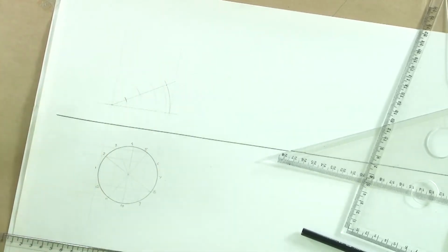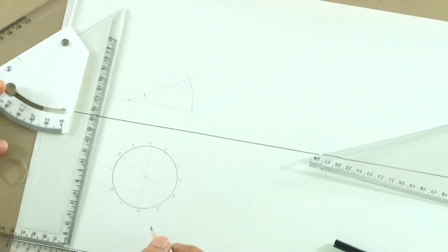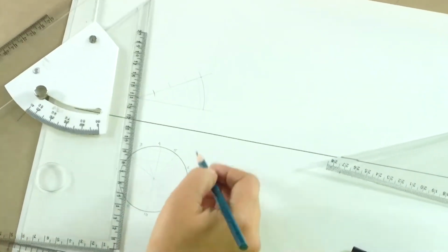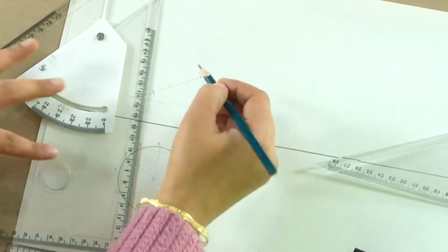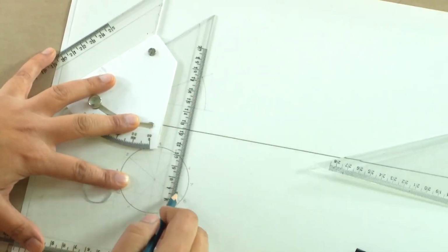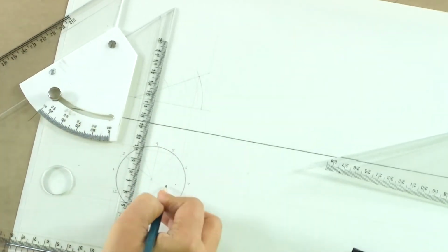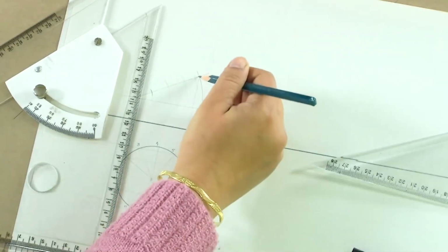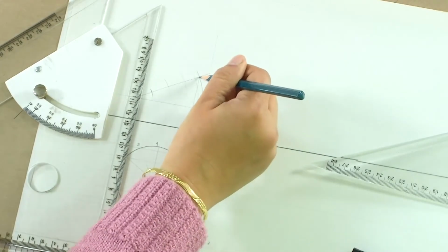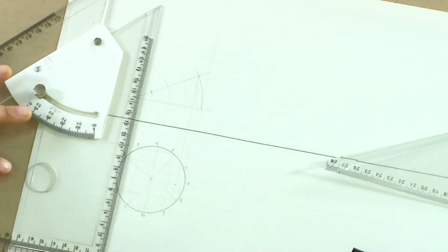The final projection is going to come now. Now we will bring back the projection of these points. So we took 7 here, now 7 went up there and it is coming down. So when it comes down, 7 meets 7 again. So the horizontal projection remains the same. The vertical projection has shifted from this point to this point, which is what we get. So this is the point 7 now.